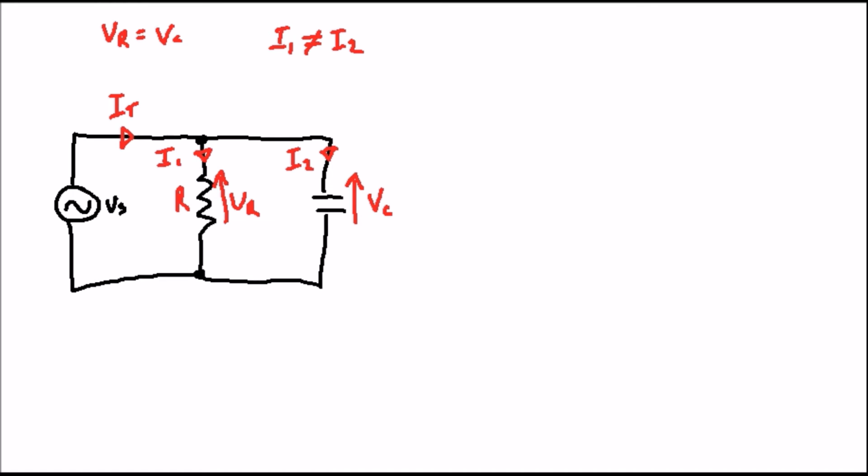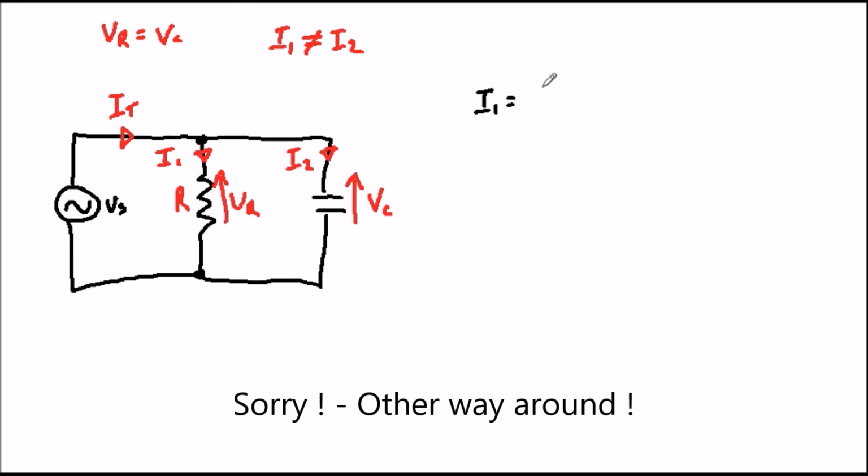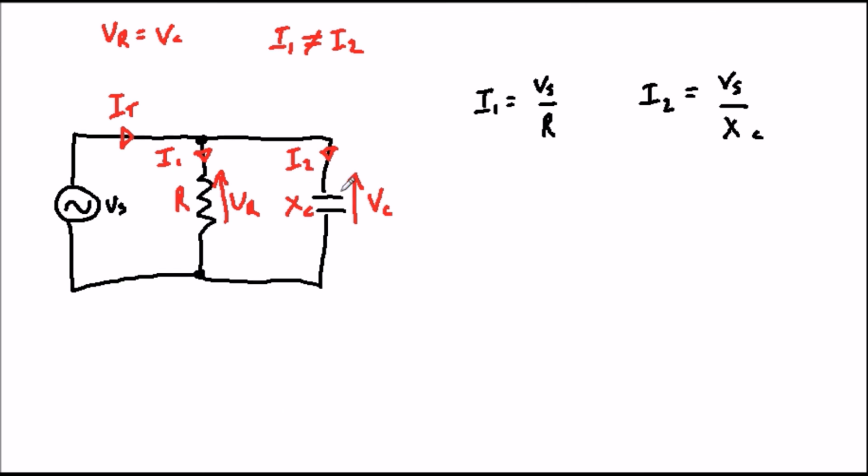So having looked at the series circuit, let's now look at the parallel RC circuit. This time the voltage is constant because it's been directly applied across each component, as we explored previously. But the current in each branch is different this time because it divides down the different branches of the circuit. The current down branch 1 is the voltage divided by Xc, and the current down branch 2 is the voltage divided by the resistance. And so we can draw the phasor diagram as shown below.